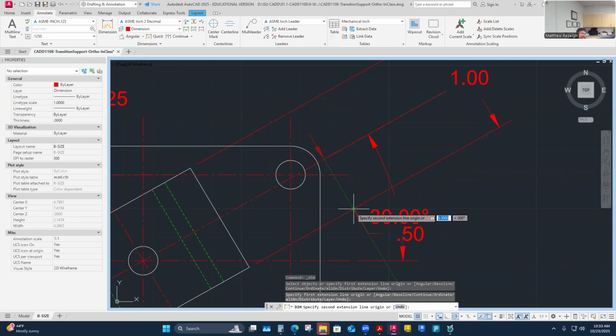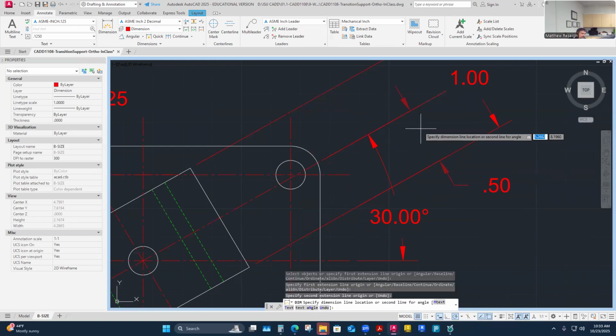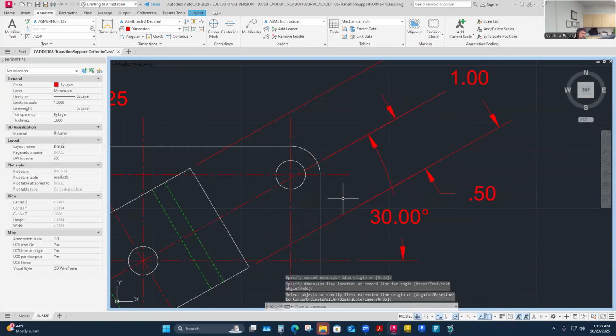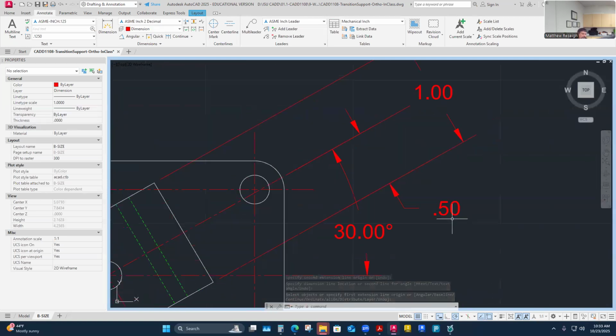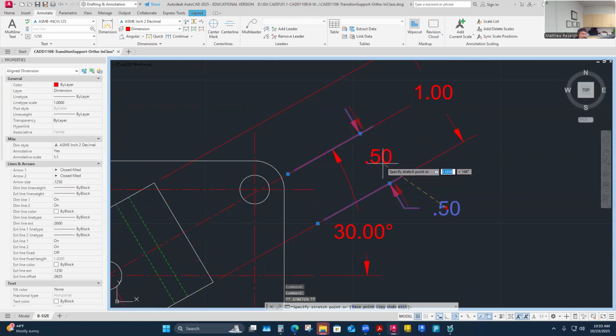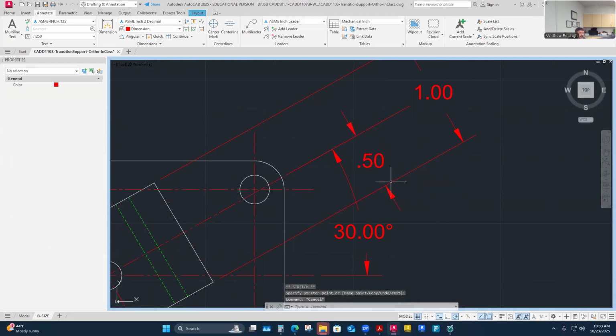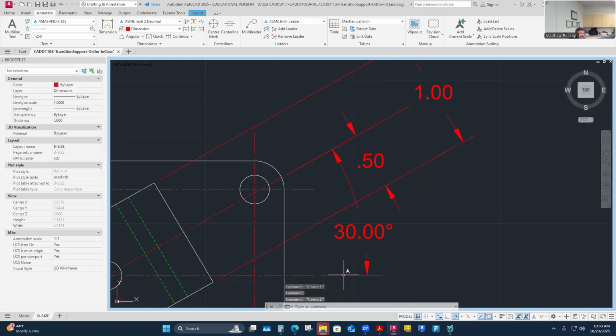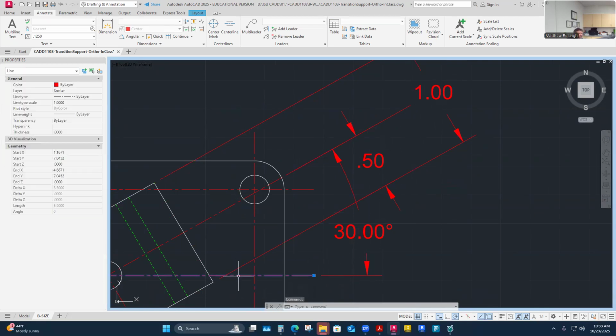Yeah, the 1 inch is going to take care of this not being a, yeah, this is going to be okay. I'm going to use their extension lines strategically. They're going to overlap on my print. You're not going to be able to tell, but this is why I'm adding this: it ties this back to a control a little bit. I'm 30 degrees up, then I'm half inch over from that, and now I'm 1 inch back this other way. So eventually I'm kind of making my way back to this datum.